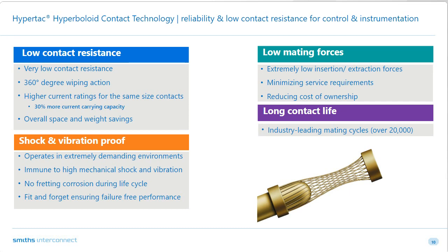Now, why is this important? You might think, hang on, it is not as vibrating an environment as perhaps I'm trying to make out. But from a connector standpoint, that small amount of vibration that you see in an overall system results, from a mechanical standpoint, in fretting corrosion. And why is fretting corrosion such a problem with the contact? Because fretting corrosion not only degrades the performance of the connector over its life cycle, but taking a complete circular view of it, fretting corrosion ultimately increases contact resistance.